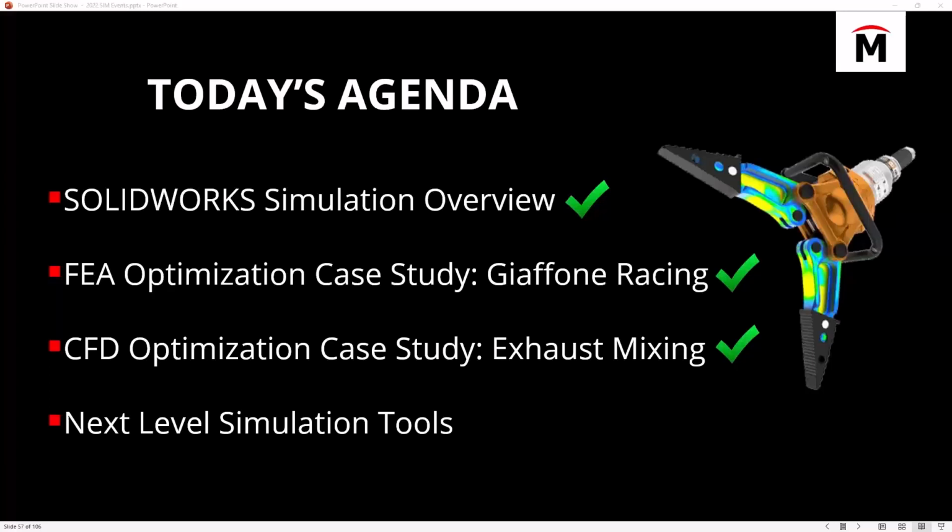Extremely low vacuums, let's say, because you actually want to do a gas flow, but you're near a perfect vacuum like space. This uses a continuum flow assumption, so the particles get so separated that it starts to break down. That's pretty rare. The other one is things that are dominated by surface tension. So capillary action, atomizing into very small bubbles where the bubble shape is held up by surface tension, this won't do either. We've actually got ways to get really close to most of those things.